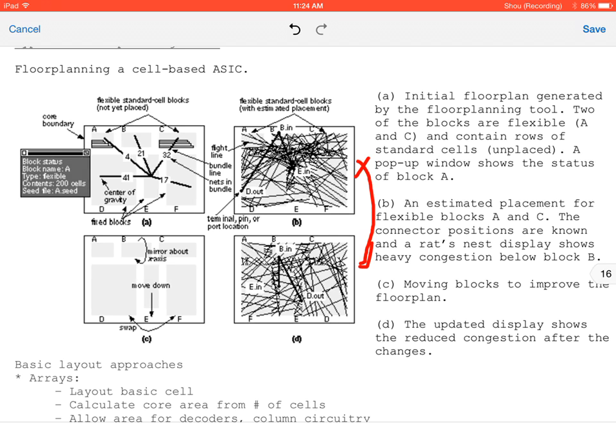So here, what they discovered, they're showing this little example, is that cell B is just mirrored about the x-axis. Everything that was at the top is now at the bottom. And by doing that, they actually cut the amount of wires required to implement the circuit in half, because now everything doesn't have to go around, you don't have to reroute things to make everything work.